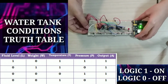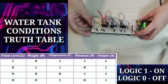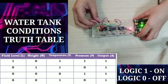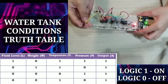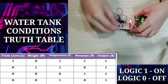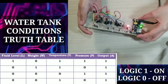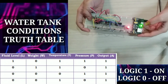Now, if our condition is that there is a low fluid level, it means that the white wire will be at logic 0, and if we have a high temperature, meaning our yellow wire is at logic 1, and if we have high weight, meaning the blue wire is at logic 1 as well. As you can see, our output will be logic 1 as well, meaning the alarm will sound, and in this case the LED is turned on.